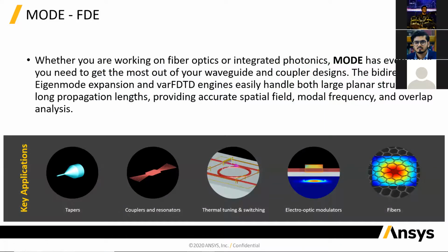The other solver, and when you think about modes, this is probably the most common one that people use, is FDE, or finite difference eigenmode solver. This solver is used to calculate the supported optical modes in waveguides or optical fibers.